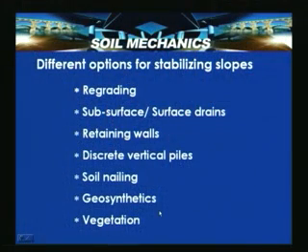In this technique, a steel bar of a certain diameter is placed into a pre-drilled hole with spacers, and then the hole is grouted. Once it is grouted, the extended portion of the rod outside is connected, and with the frictional interaction between the grouted portion and the soil, and due to tension in the nail, it gives a stabilizing effect to the slope. Then another aspect is geosynthetics, and recently vegetation or biotechnical stabilization is gaining momentum.